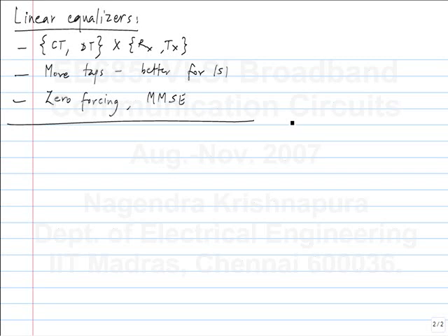Those of you who have done communications know that if you send a pulse through noise, then you have a matched filter whose response is the time-inverted version of the pulse that you send. In case of a rectangular pulse, that combined response is simply an integrator. Okay, so that will probably be better. Yeah. Also, when you do integration over one time period, like this is for wireless and things like that.